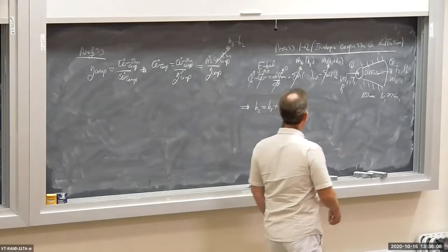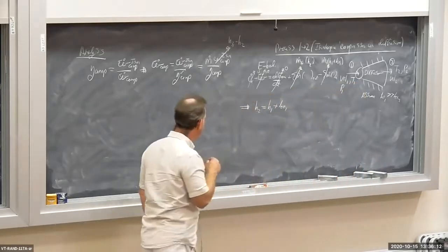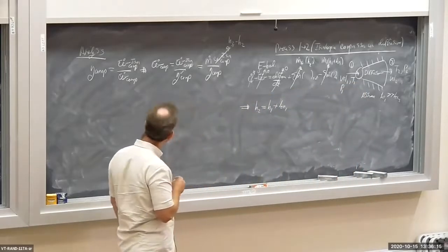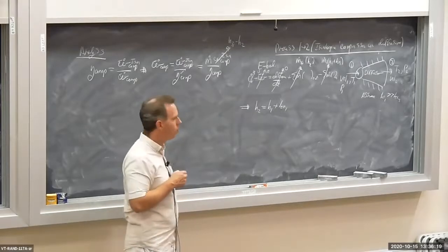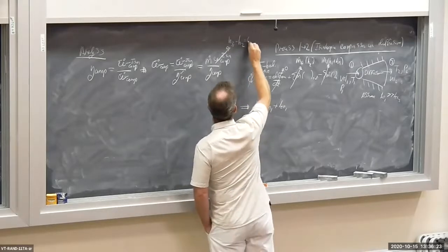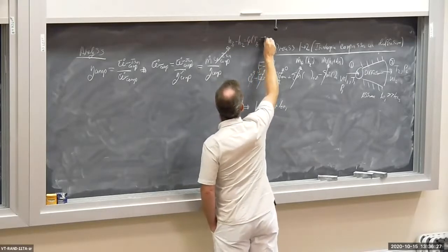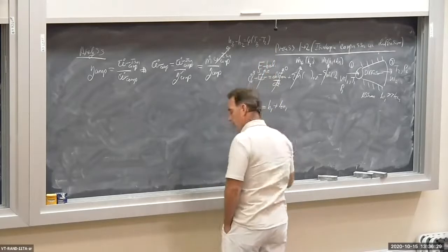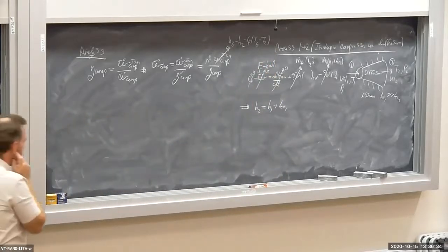What's H1? Well, actually, we're not going to worry about that quite yet. Oh, this is a constant specific heat problem. That means that this is equal to Cp times (T3s minus T2). So I want to find T2, not H2.